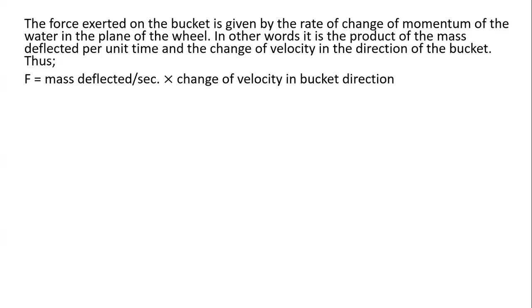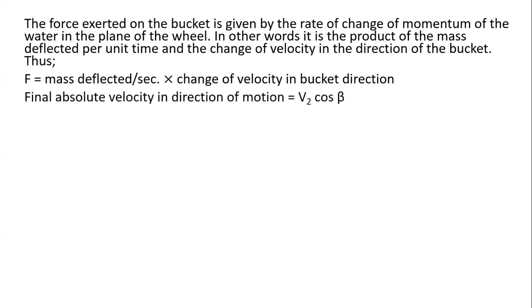So here we say mass deflected per unit time multiplied by the change in velocity of the bucket. Mass deflected per unit time is going to be given in kgs per second. The change in momentum, or rather the change in velocity, is going to be just the difference in the velocity. So U minus the other velocity.